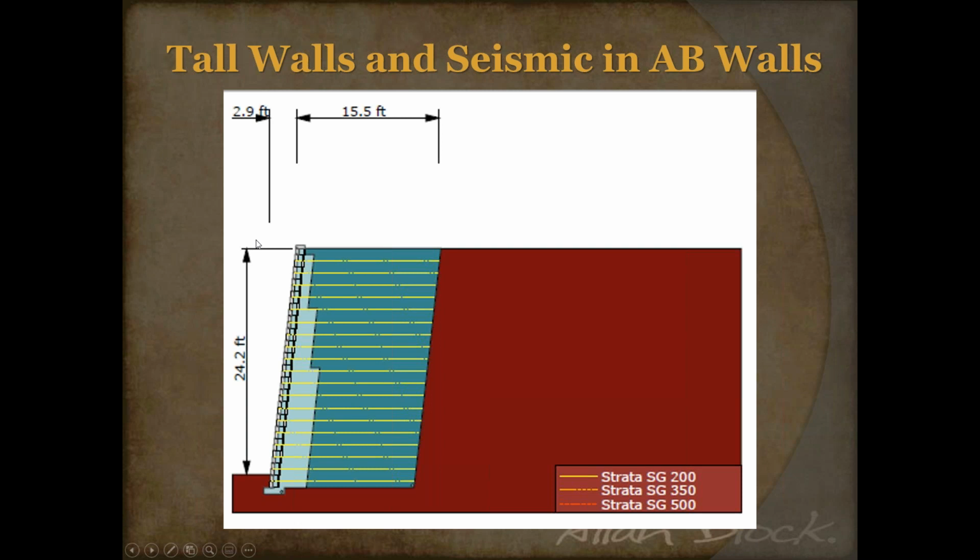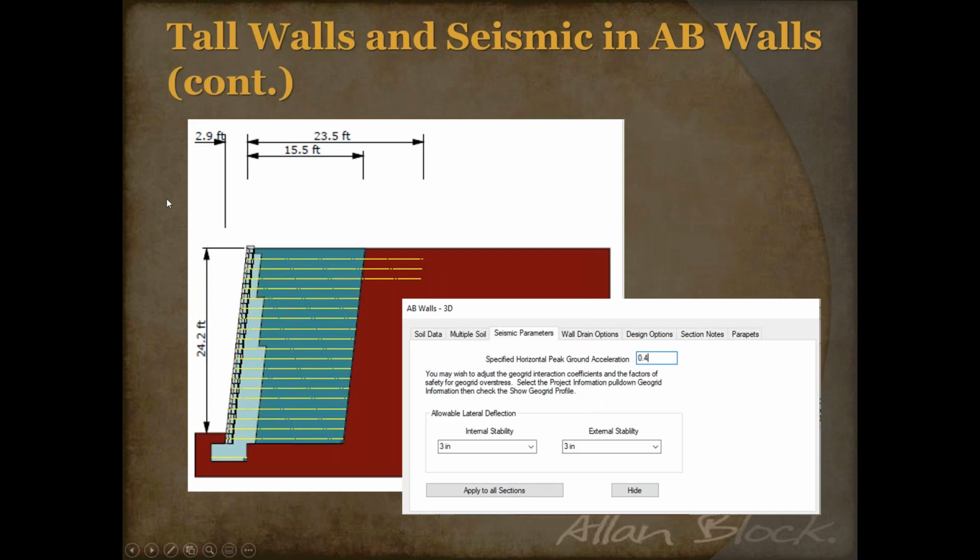And that's another great thing about using our software: you don't have to consider doing these things by hand, and it's easy to forget simple considerations like these. And then we also can incorporate our seismic. That's done using a peak ground acceleration value. You can see I input a 0.4 for the wall this time. Again, that's typically the higher end of the values that we see.